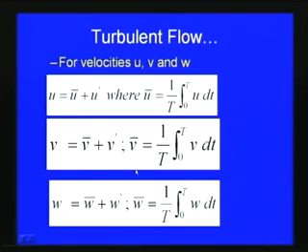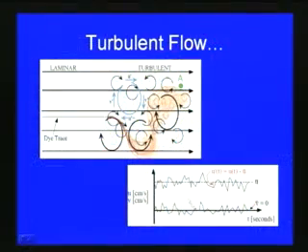So, this is how we express the various velocity components u, v and w, and in a similar way we can express the pressure and other components with respect to a mean component and the fluctuating or instantaneous component. This is clear from this figure. You can see the velocity in x and y direction, u, v, is represented here.